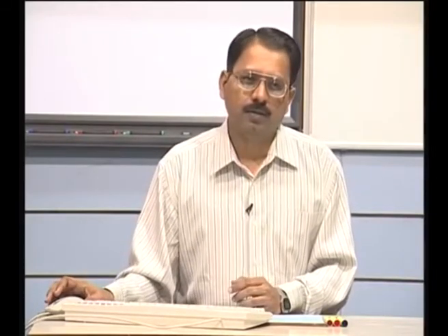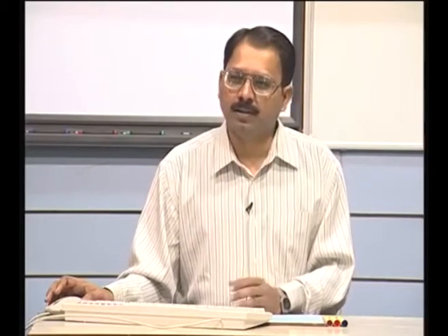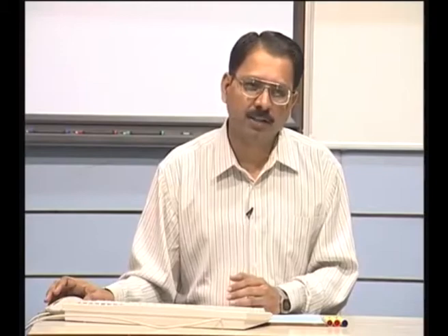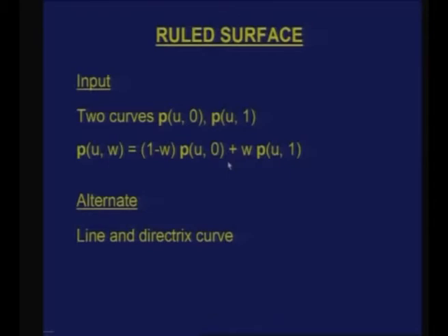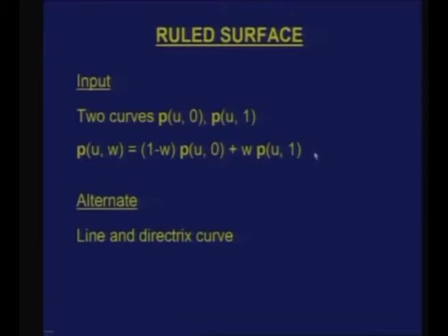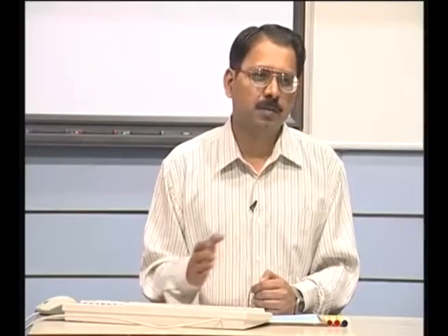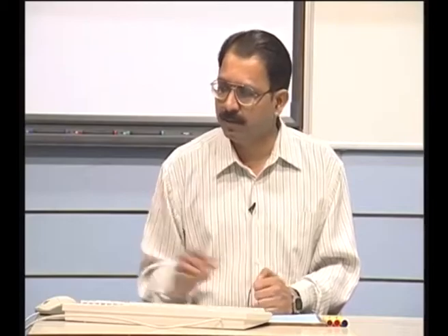Now, ruled surfaces are very popular in many design and manufacturing applications. The reason is very simple: the definition is very simple. Firstly, you are defining just two boundary curves and linearly interpolating, so the mathematical definition is very simple. This is just like extending the parametric representation of a straight line, which basically interpolates. If I put this as a point, this becomes a straight line, whereas if I take curves, it becomes a ruled surface. Mathematically very simple, easier to program and easier to compute many of the values.